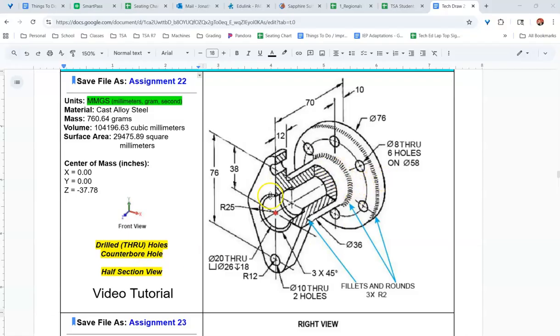It also demonstrates an alternative view. This drawing is also part of the examples where I just went over alternative views, and I'm showing a half section here. So a quarter of it is removed, and if I were to look at this from a side view or a top view, it would show that only half of this was section viewed or removed away. So it's showing the internal of this pipe. We basically have a part out here, and then there's almost a connecting tube, and then back to what I would call a flange in the back of it.